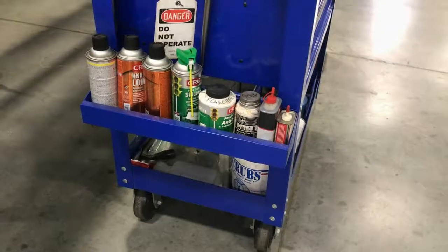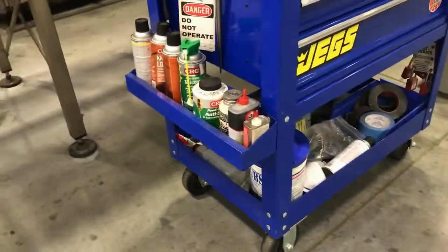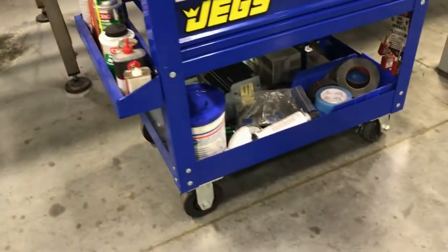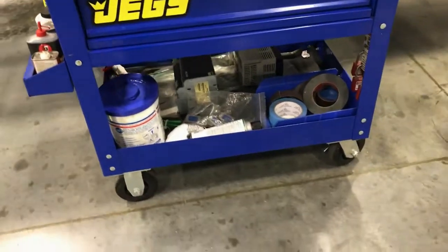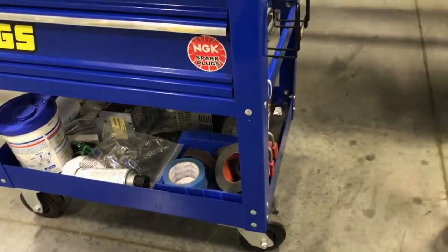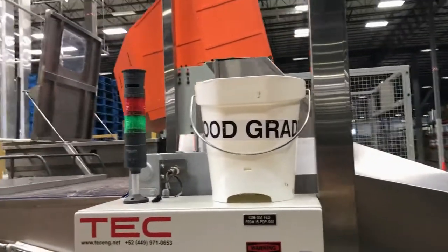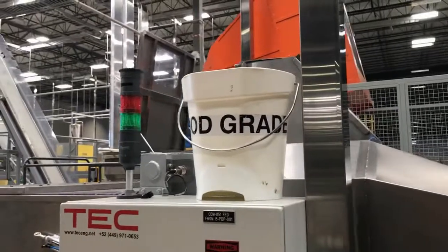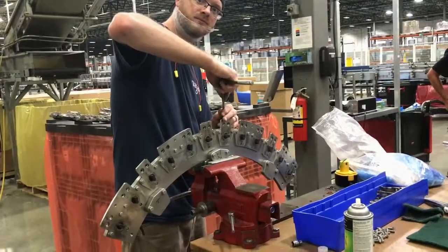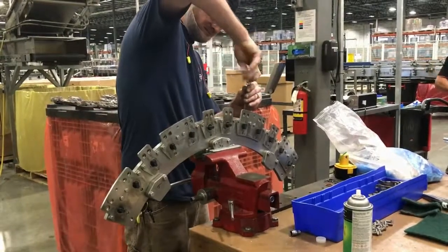Another policy we use for maintenance is the Line Lubricant Policy. This is a set of guidelines on when and where to use lubricants near preforms and bottles. All lubricants used on the lines near caps, bottles, and preforms are food grade. This means they are FDA approved to be ingested in small amounts if some residue unintentionally contacts food. Even though our lubricants are food grade, we try to avoid any contact between product and lubricants.